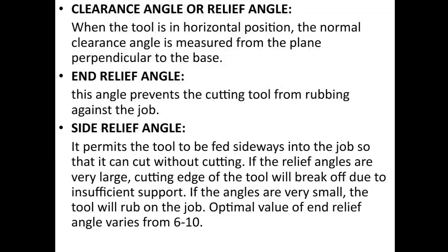Clearance angle or relief angle. When the tool is in horizontal position, the normal clearance angle is measured from the plane perpendicular to its base. End relief angle. This angle prevents the cutting tool from rubbing against the job.